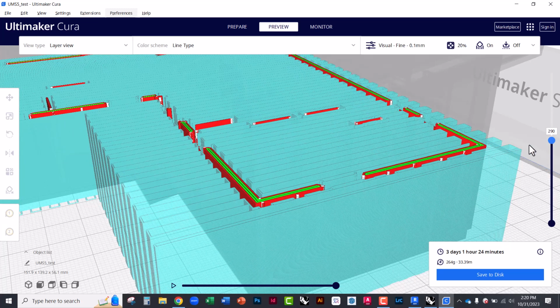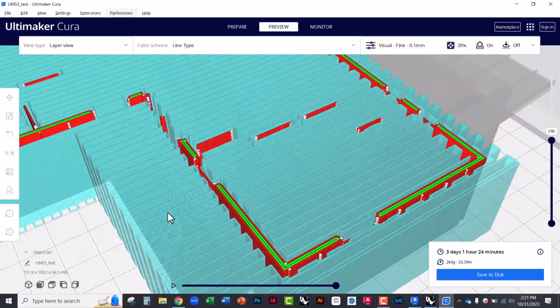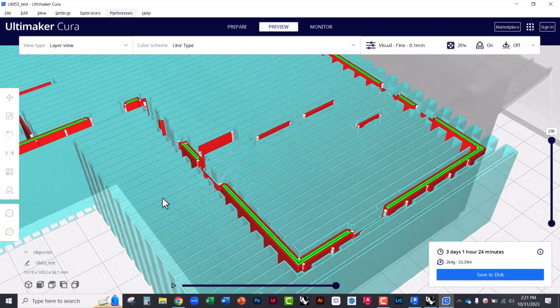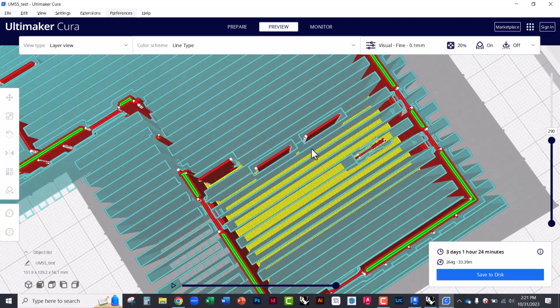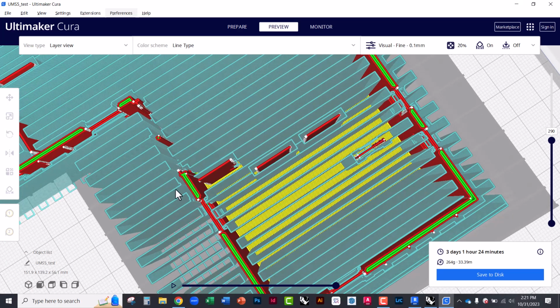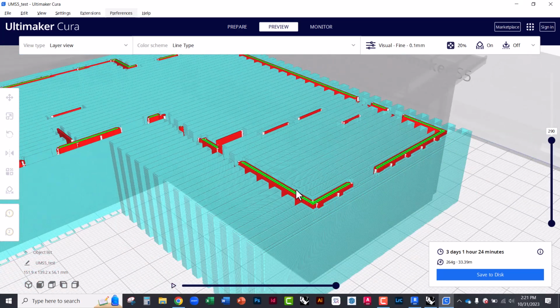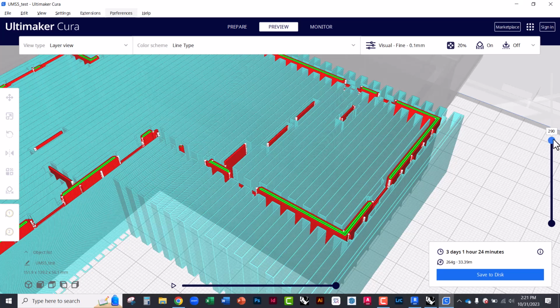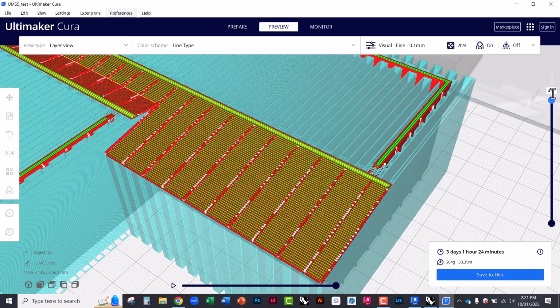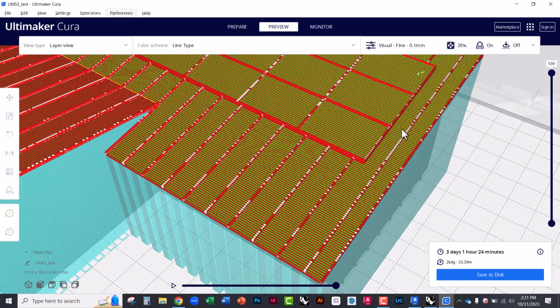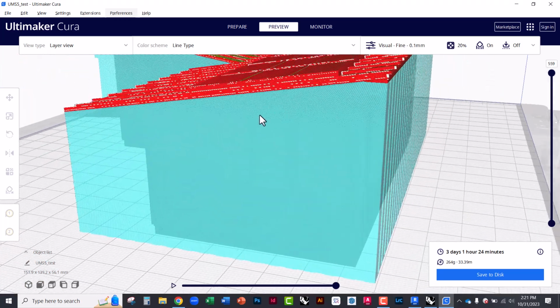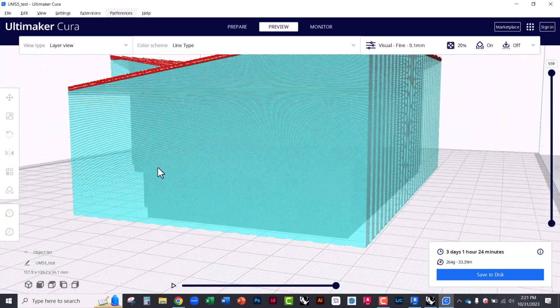but if this were to print as it is now, it's going to try to print support material, which you see in blue, throughout this whole house. You're noticing it's going back and forth with this blue support material. The reason for that is because we have overhangs, because this roof that you see here is overhanging the rest of the model.